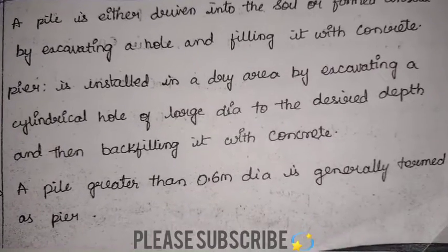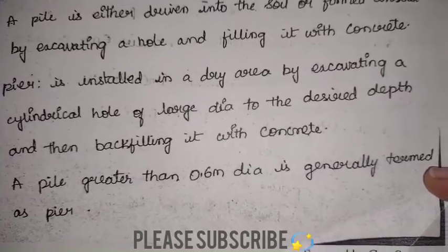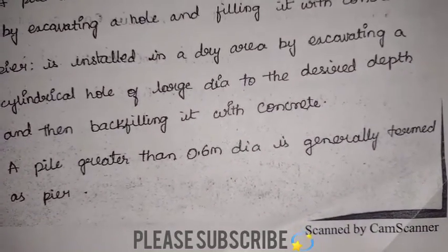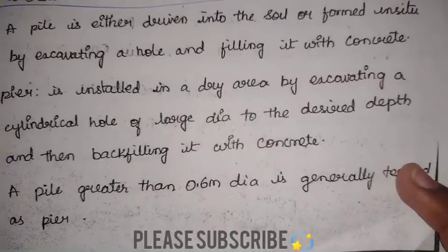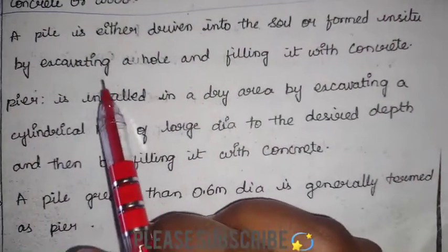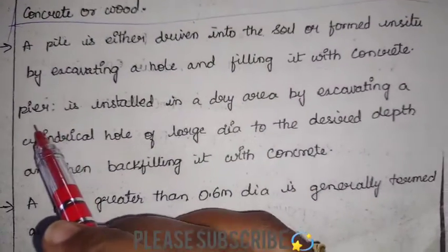So here we go for pile foundation whenever the soil near the ground surface is not capable enough of supporting the structure above the foundation. So here we'll be using some deeper foundations like piles, piers or caissons. So that will be transferring the load to a greater depth. A pile is either driven into the soil or formed in situ by excavating a hole and filling it with concrete.